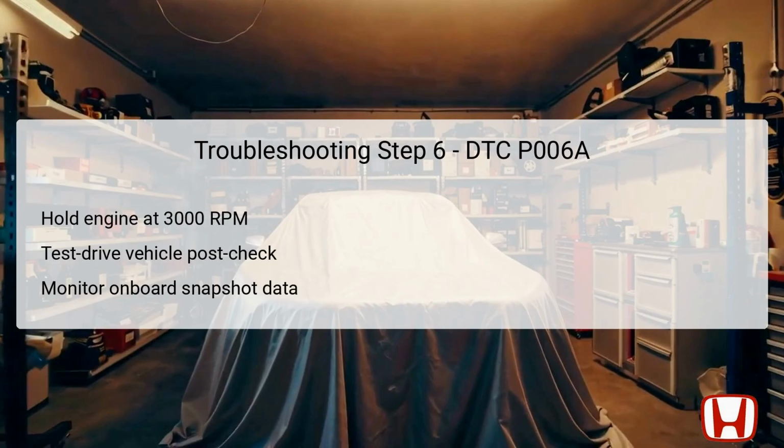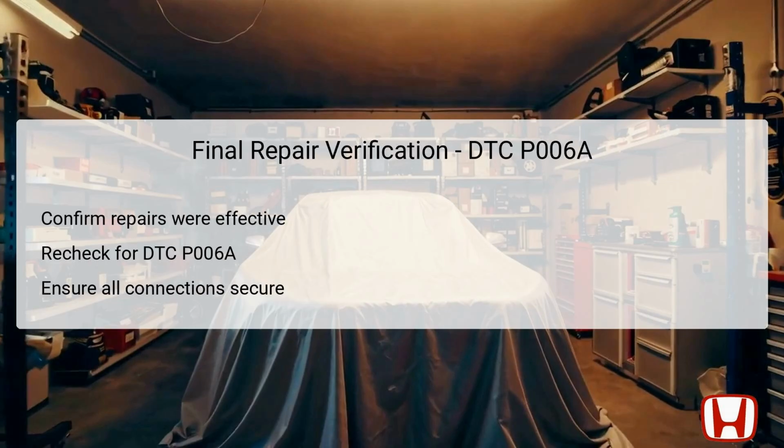Post-test drive, the HDS will indicate the OBD status for DTC P006A. If it returns as failed, then a replacement of the MAF sensor or IAT sensor 1 is required. However, if it indicates passed, the system is functioning properly at this moment, but checking for intermittent connections is still crucial for ongoing diagnosis.